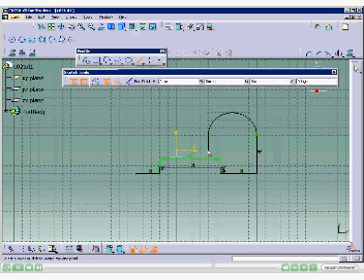Select the end point of the previous line as the start point of the fourth horizontal line. Move the cursor horizontally toward the left. Click when the length of the line in the Edit box of the Sketch Tools toolbar shows a value of 80 mm. Next, select the end point of the previous line as the start point of the incline line. Now select the end point of the incline line as the start point of the next line.